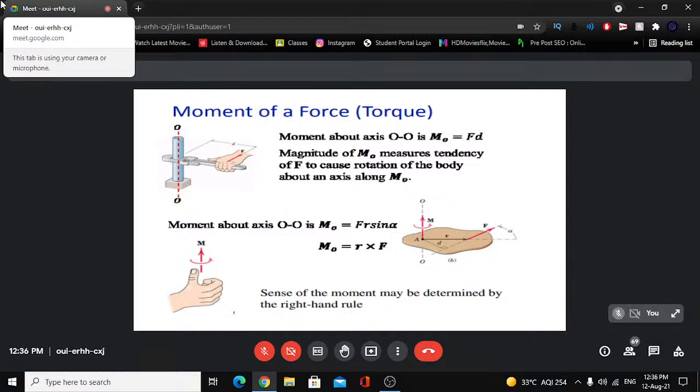In that case, here it is a circular cross section. So the cross-sectional axes are on a plane perpendicular to axis O, and on that plane there will be two cross-sectional axes. Moment about those axes we define as the bending moment, because that causes bending. But this moment causes twisting, so we call it torque. Now moment about O, how to get that? This is what we have to study here.